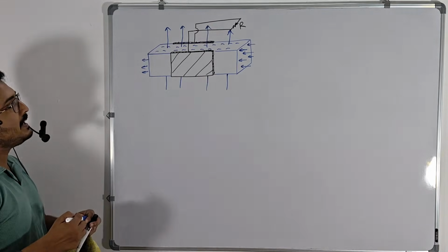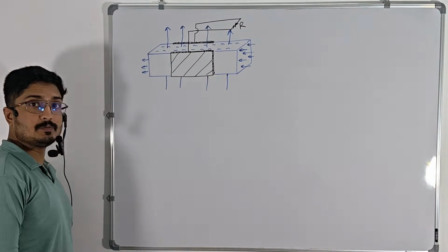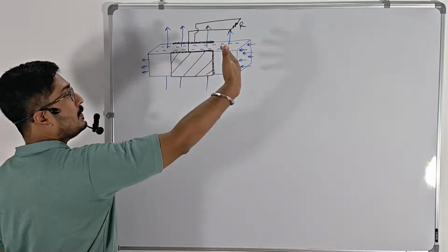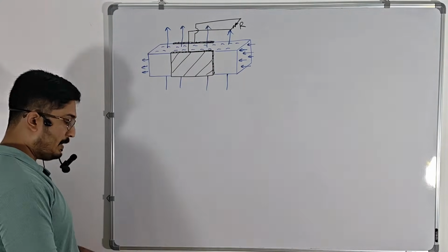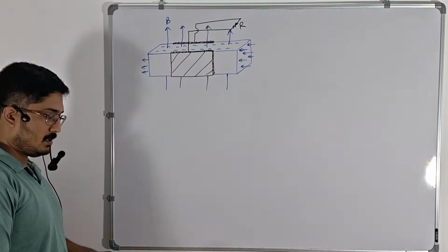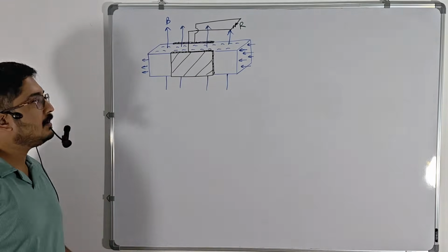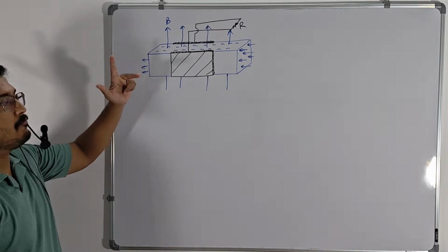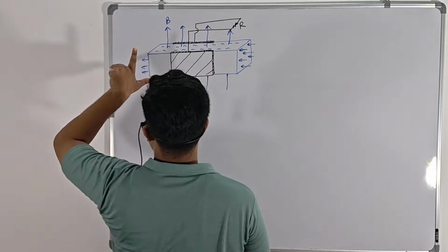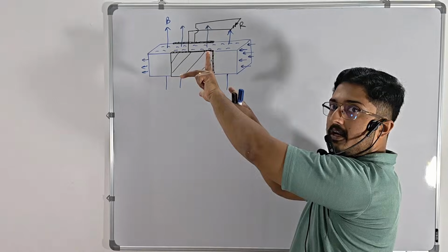Now, because of this magnetic field, when a conducting fluid, specifically mentioned, is passing between these two plates through this magnetic field, there will be a force applied on the conducting fluid. So, can you imagine which direction this force will be? Magnetic field is upwards. The fluid is moving not this direction, but that direction. So I rotate like this, and when I do that, I find that the force is acting inwards, right?